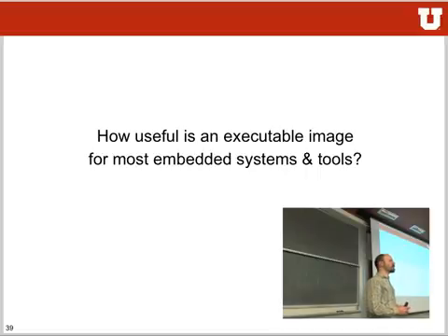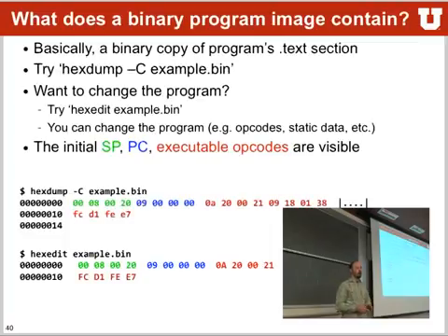Yes. These executable files are really important for debugging, because without them, you don't really know what's going on or what the different C instructions mean. So the executable file is really the link between your C code, your assembly code, your source files, and what's written in your binary file later on. So then, what does a binary file have in it? So once you send it through object dump, you can look at it again, and no big surprise really, right? We have the stack pointer, the first jump address, and after that comes your program.